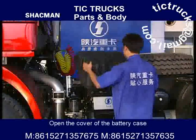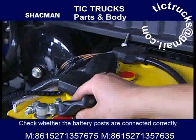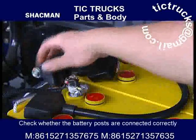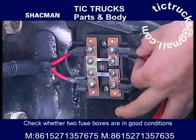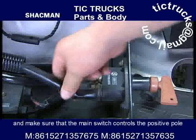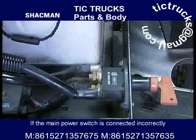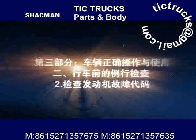Open the cover of the battery case. Check whether the battery posts are connected correctly. Check whether two fuse boxes are in good condition. Check the connection of main switch and make sure that main switch controls the positive pole. If the main power switch is connected incorrectly, the ECU electronic control unit of engine may get burned out.